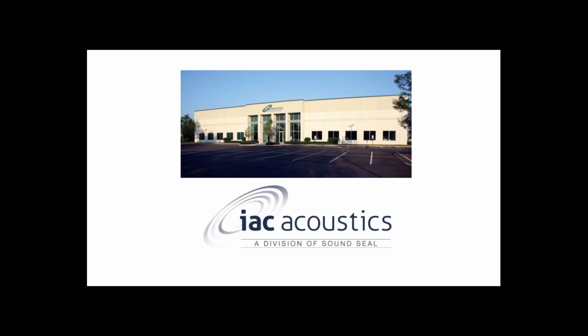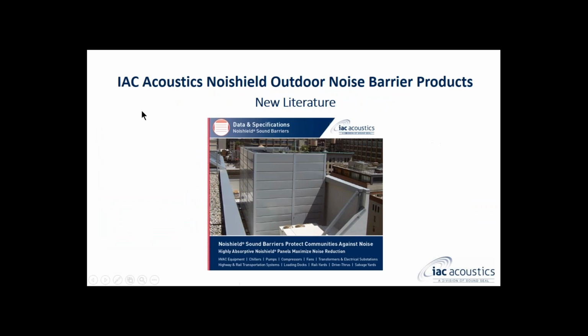I also have a question from the audience that involves the sound absorption coefficients and some of the values that might have been greater than 1. And that certainly can be the case. Sometimes during testing, because of the limited sample size and the potentially small room that the tests are conducted in, the math that's involved doesn't give a completely accurate representation of how much sound absorption is taking place.